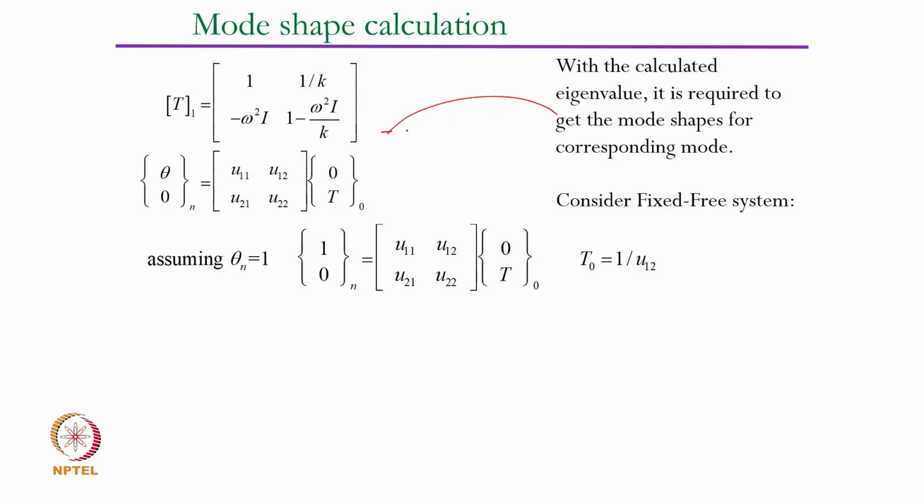For example, if the shaft is flexing with respect to this, if this is treated as maximum 1, then how much is this, how much is this, how much is this, that is basically your mode shape. So in this torsional vibratory system, we say that at the end there was a flywheel here and then there were so many elements here. At the end, if this deflects theta equal to 1, in relation to that 1 unit twist, what are the twists in the rest of the elements? So when we assume this theta at n equal to 1, we still do not know how much the torque value is.